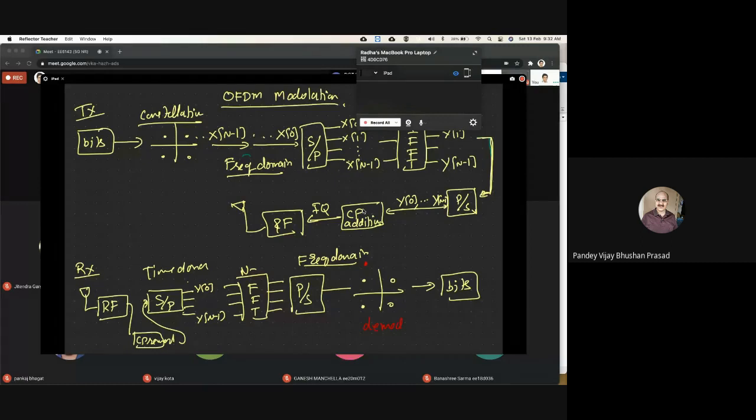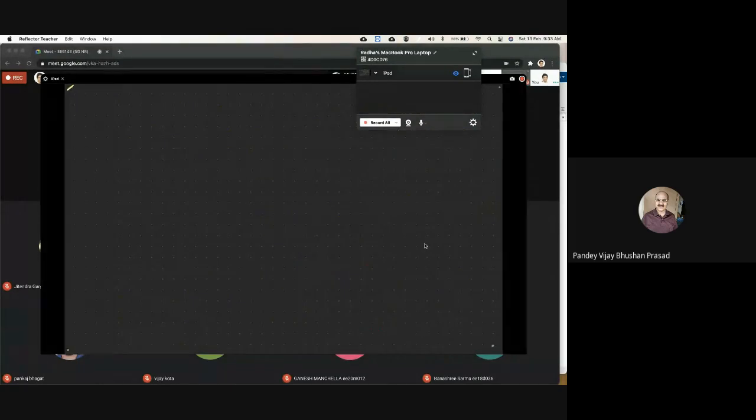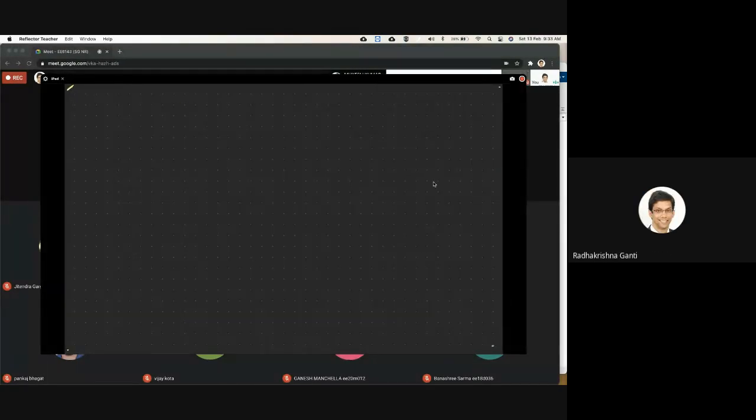Sir, the last class you said that for a signal having bandwidth of W, the sampling frequency will also remain W. So here I want to say that in case of our voice, which goes from 300 hertz to 3.4 kilohertz, including guard band, you can take it up to 4 kilohertz. So in place of sampling at 8 kilohertz, can we do it at 4 kilohertz? No, sir. Essentially, it's a question of understanding how you define your bandwidth, sir.